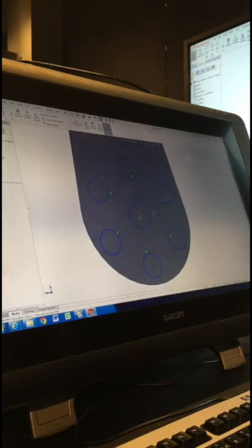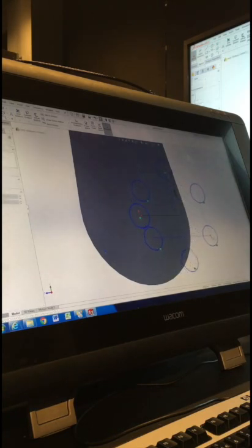So the tricky one, even though it looks like it's sort of fully defined, well, these lines down the bottom, if I click one of those circles, like the center point of one, and drag it, you can see how it moves to the side. All right, all I have to do is click that construction line, which is at the center, and just drag that back to the origin. Snap it to the origin, and then that line itself I can make vertical. Okay, and that's sort of starting to define that pattern.